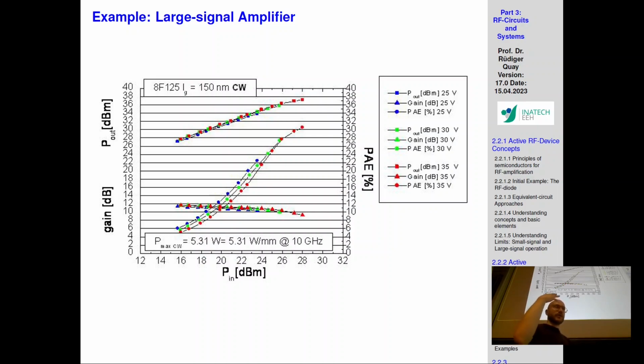So a lot of your applied DC power at the drain source voltage will be dissipated into heat. We discussed it beforehand. Heat is a problem. Heat is managed via packaging, and whether it is flip chip or on the submount, it's always a question of heat dissipation.